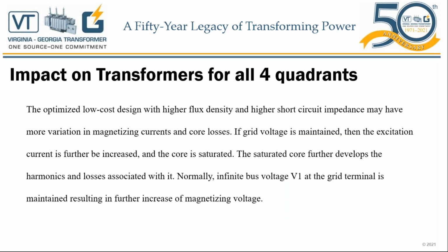A couple additional notes on the core performance and core design for the transformer that we were just talking about on the previous slide. The temperature rise limit for the core per the IEEE standards is 130 degrees C. And the cores are designed to run at 105% plus load plus the 0.8 power factor. Another additional note is that the transformer cores that we design are designed to run at 110% of the rated voltage under no load operation. Once again, under no load operation.